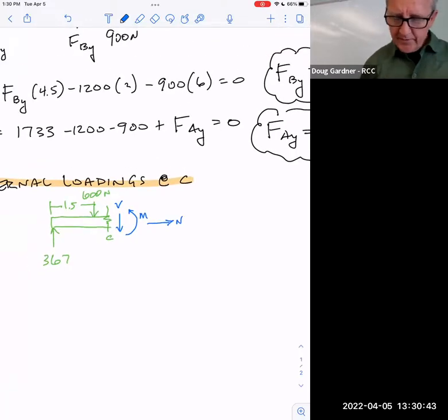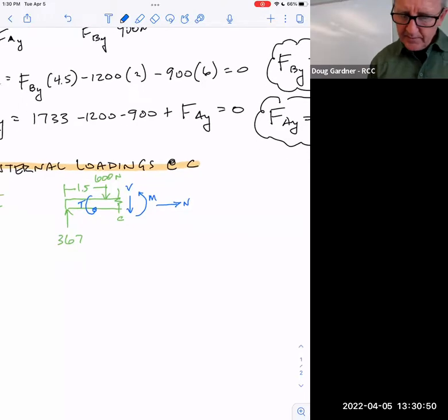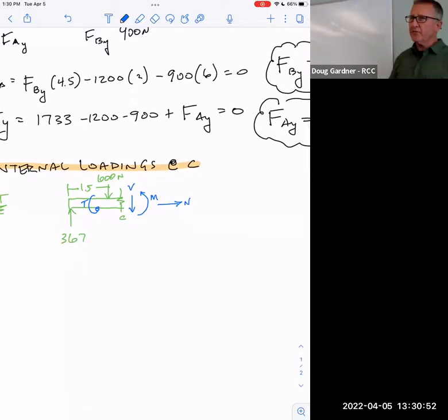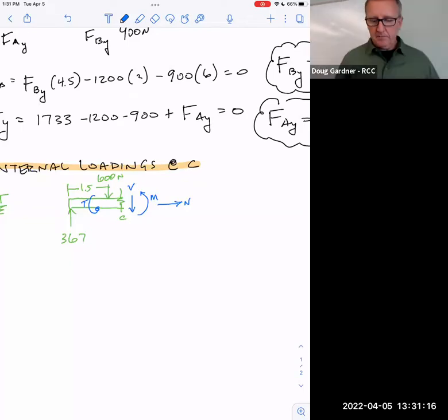And then there won't be a torsion either, but I think I'll go ahead and draw it in. There will be in later problems we do today. So do you agree there's no forces trying to twist that? You should even be thinking what kind of force would twist it. I can't even understand what would even do that. But what would do it is if that wasn't something circular, but like this book right here. What if I had a vertical force on it that was way over here? Isn't that trying to rotate it now? So then that would twist it. But right now we're just doing kind of a 2-dimensional problem.